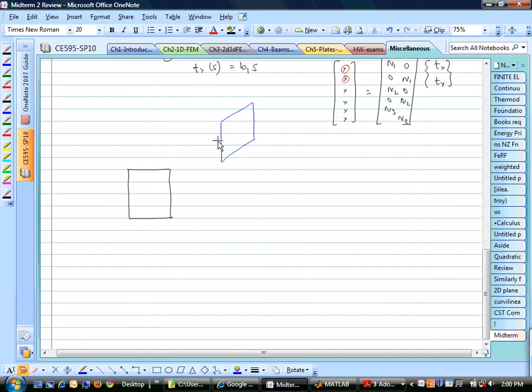If you have some distortion, maybe your actual element is not a parallelogram, then you can see that in some of these regions the stretching of that element is much larger, whereas this angle remains close to 90 degrees, so the value of the Jacobian will be different at different points. And I could give you the 4 coordinates and ask you to calculate the Jacobian, similar to your homework 6.